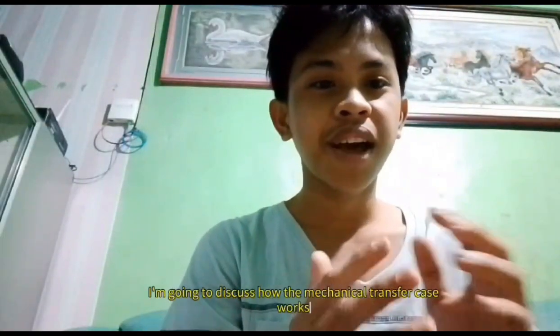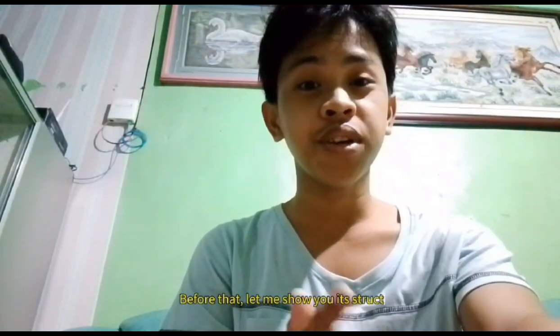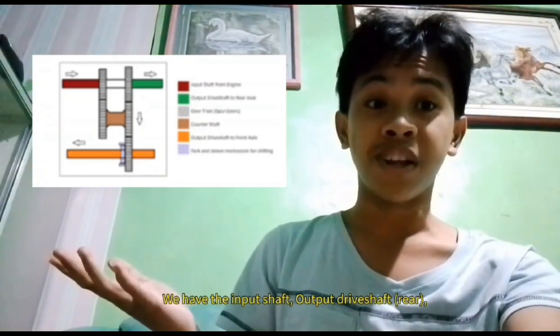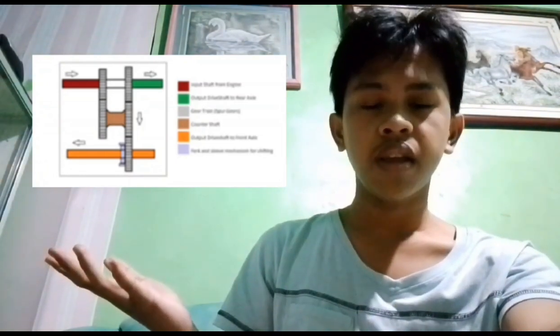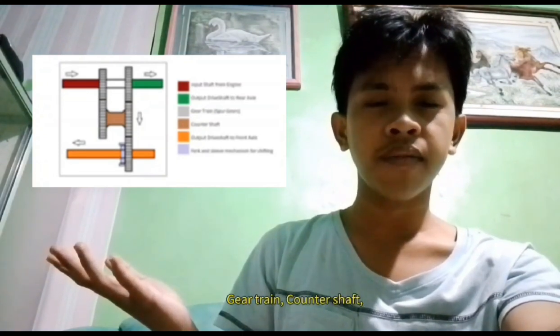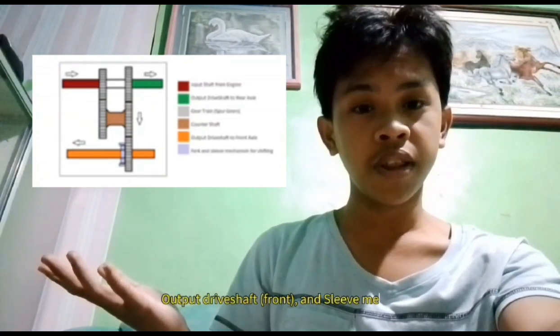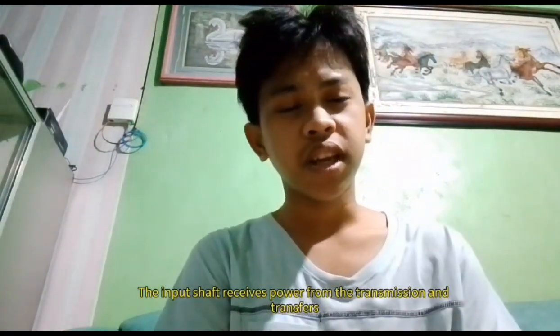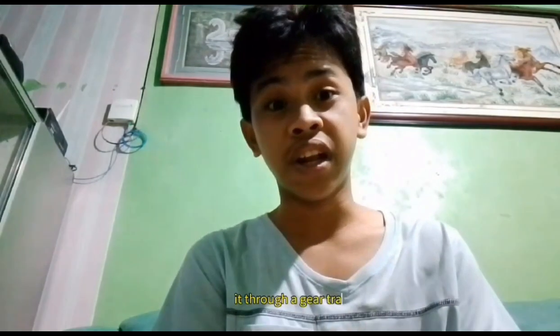Hello everyone. For now, I'm going to discuss how the mechanical transfer case works. Before that, let me show you its structures. We have the input shaft, output shaft, output drive shaft for rear, gear train, counter shaft, output drive shaft for front, and sleeve mechanism. The input shaft receives power from the transmission and transfers it through a gear train, which